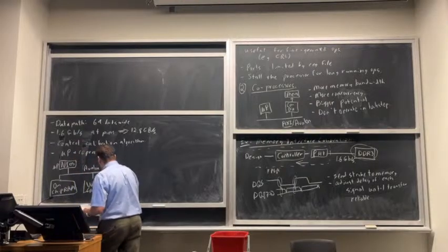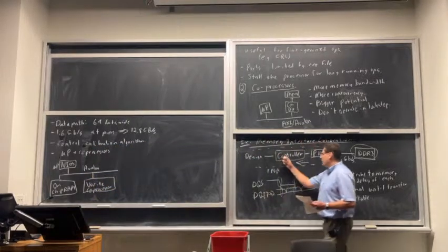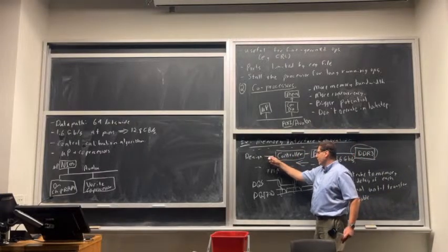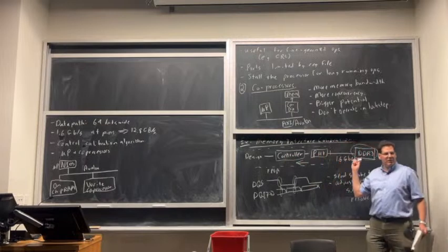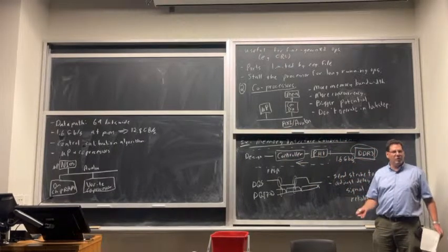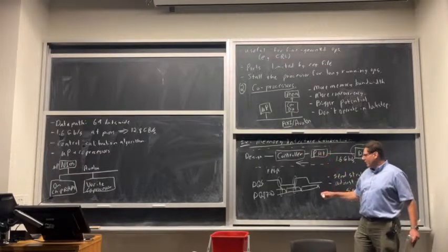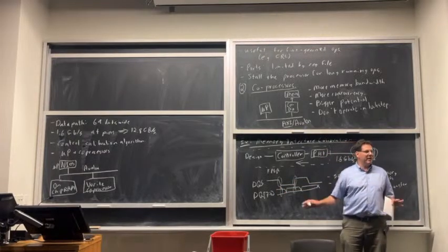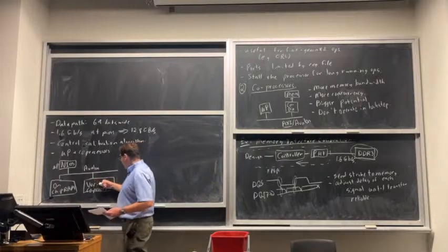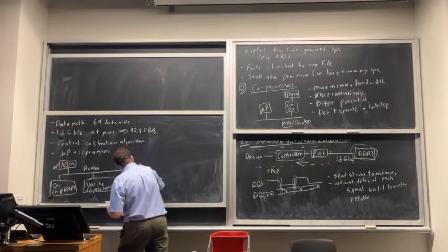Okay, so if there's a write command, basically the controller knows how to turn high-level commands like read from this memory address or write this memory address, into the low-level commands that DDR actually understands, because it actually wants to say here, activate this row, now write to this column, that kind of thing. So the controller does that. The PHY basically gets all the timing and signals exactly right. So this write coprocessor is responsible for getting all those timing and signals right. And the same thing for this read coprocessor.